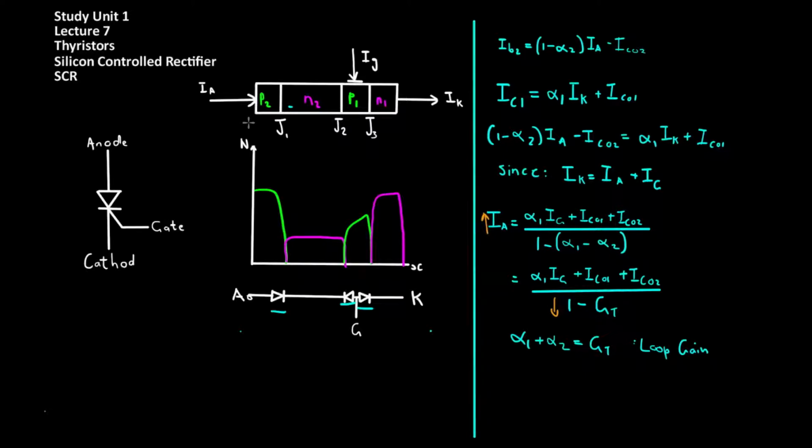The device can also be turned on by inducing a ramp at the input where the maximum value of the ramp is less than the forward bias voltage of the junction. This behavior will effectively induce current flow across junction J2, which in turn encourages the regenerative effect, which increases both alpha 1 and alpha 2 and turns the device on.